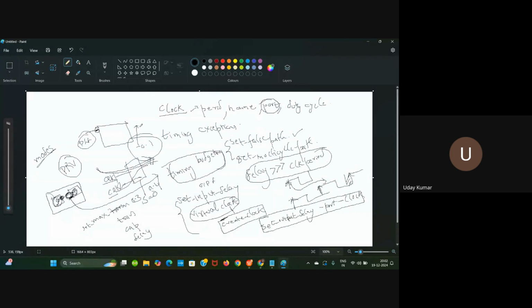This is a precaution. You are telling the tool that if you exceed this value, then definitely somewhere the timing will degrade. So you are cautiously telling the tool using SDC: do not optimize in such a way that this max transition value might increase beyond 0.3.